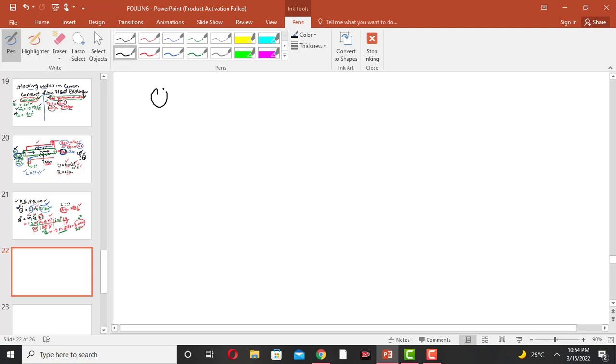So the energy given by the hot geothermal fluid is Q, which is 301 kilowatt, and by energy balance Q is equal to the mass flow rate of the hot geothermal fluid which is flowing inside the shell, the specific heat of the hot fluid, and the temperature difference of the hot fluid.